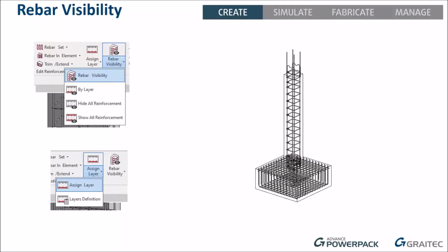So, these are very clever view specific tools which make setting the visibility of rebar very, very easy. And these tools don't just relate to reinforcement that's created using the PowerPack. These tools can also be applied to reinforcement that's been created inside of Revit using the standard Revit reinforcement tools.